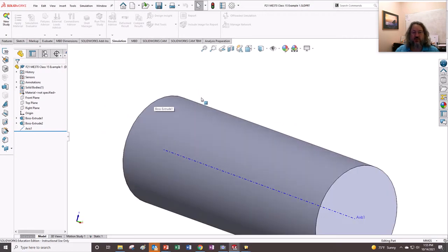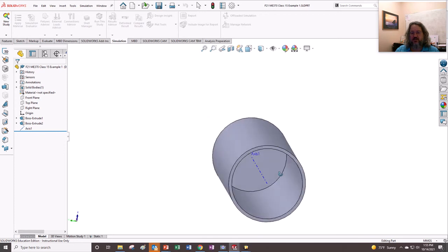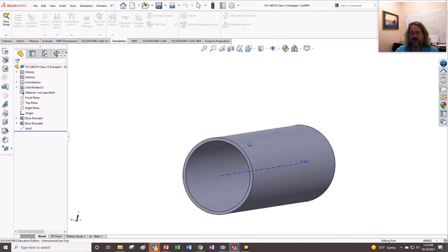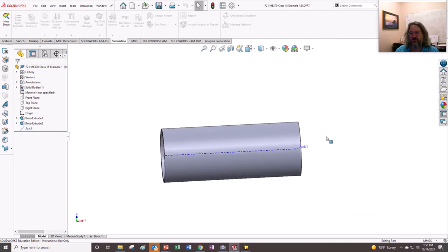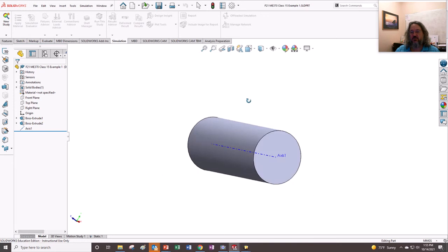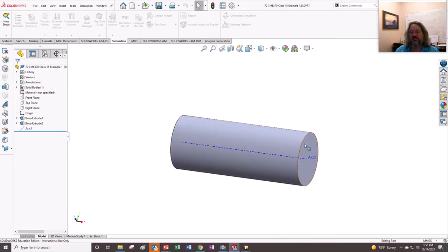I did it in two different ways, right? So first off, I made a solid element model. This is all the dimensions, and they didn't tell us how long the thing was, so I just picked it to be like 500 millimeters. I just needed this to be sufficiently far away from here. I also made this end cap the same dimensions, so it just needs to be something there, otherwise we won't have longitudinal stress.